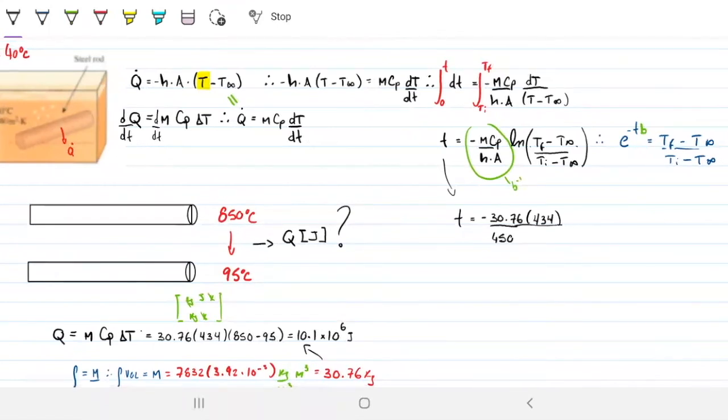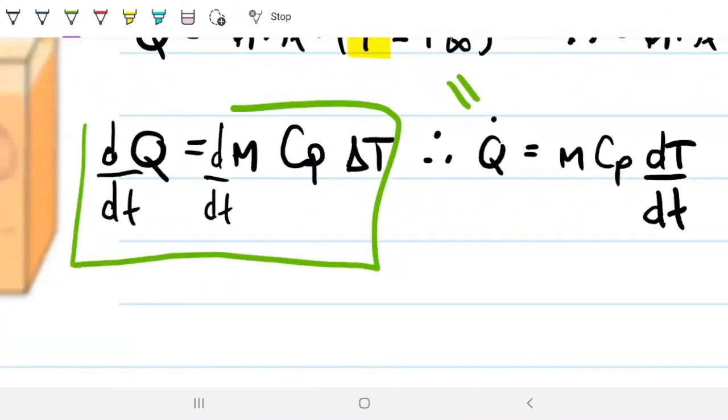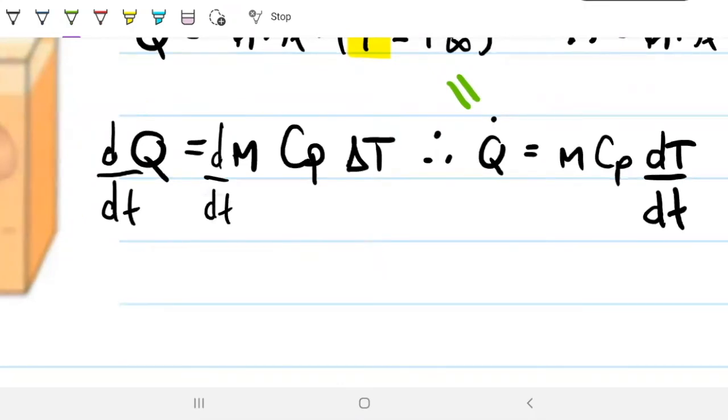Sorry, I have a question. My internet cut out. Can I ask just one question from the beginning? Now, I understand the Q minus H times the area, but did you just multiply it by the dt to be able to differentiate it, or on what basis did you differentiate the equation? I derived it here in the beginning in respect to time. So I took both sides of the equation in respect to time. So yeah, okay, you differentiated both sides of the equation with respect to time, and that's it. That's it, yes. And this gave me the heat flow, the rate of heat. And on this side here, because the mass and the CP came out, this just gave me dT. Yep, so I left it in the form of the derivative.